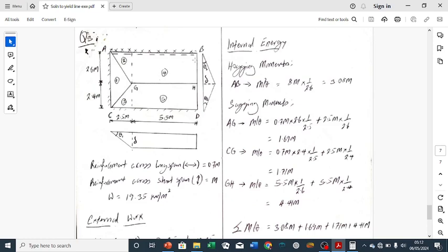So having done that, you also will notice that the whole of plate 2 and 3 will rotate about AB. The whole of plate 3 and 5 will rotate about side CD, while plate 1 will rotate about side AC. There is nothing rotating about BD because BD is unsupported. Always take note of that. So this unsupported edge influences the selection of a yield line pattern. So these are just cutting sections to see, so you might not bother yourself much about this.